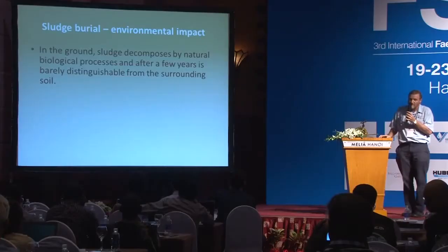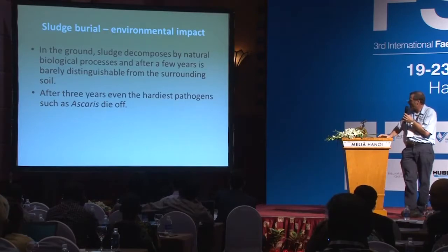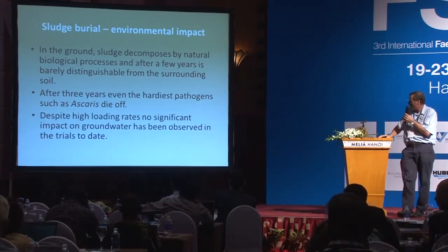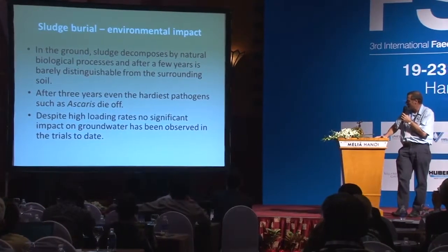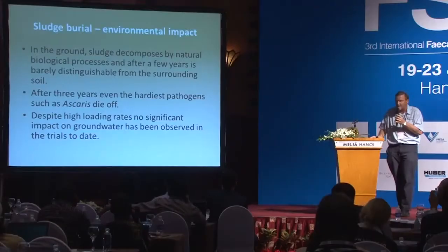So, concluding now, the environmental impact of sludge burial in the ground: sludge decomposes by natural biological processes. After 3 years, it is barely distinguishable from surrounding soil. After 3 years, even the hardiest pathogens die off. And despite high loading rates, no significant impact on groundwater has been observed in our trials. And I've urged everybody who is interested, please go and do your own trials. I'd love other people to investigate these things.